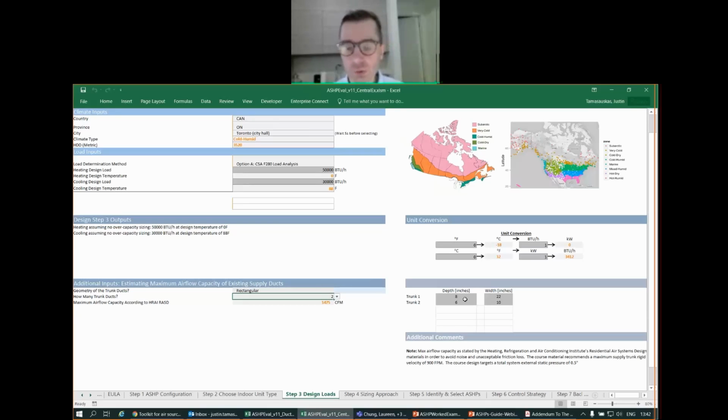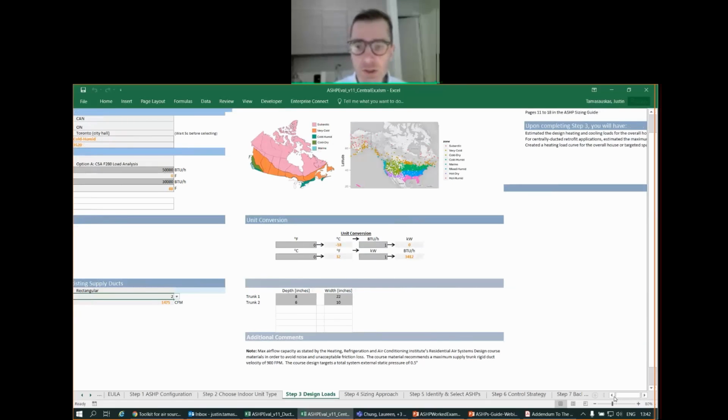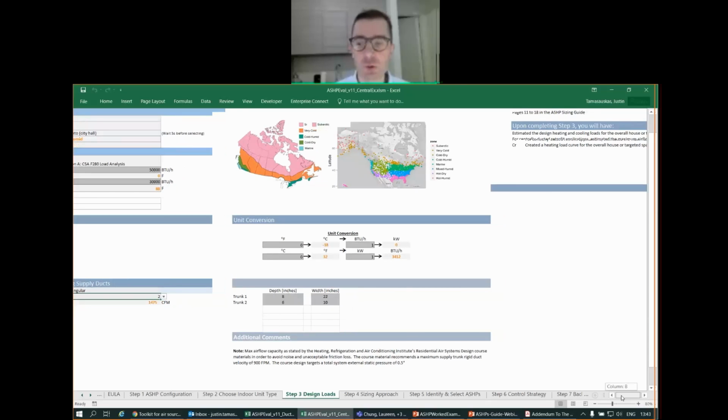And so what the tool does is it takes that information that you enter and it does a calculation to determine what the airflow capacity of your ductwork is, based on a maximum trunk velocity of around 900 feet per minute, which is derived from the HRAI Residential Air Systems Design course.